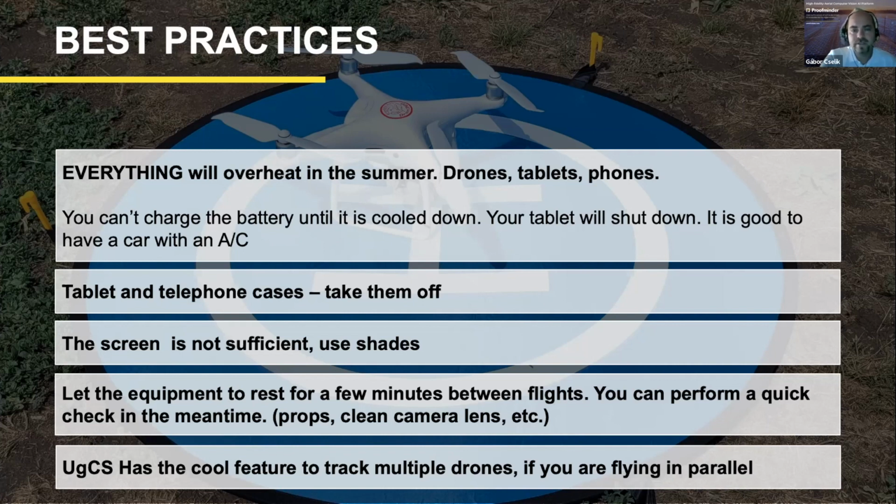And as I said earlier, if you are doing some check on your drones, or if you are copying files to your laptop, let the equipment rest for a few minutes. It's just a matter of minutes really, but it can help. Sometimes we face the issue that the Phantoms' sensors were a little bit too hot. They were overheated and they sent some false data. But if we let them cool down a little bit, we didn't have these problems anymore.